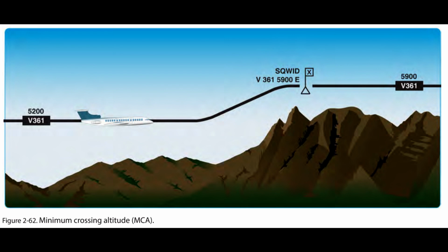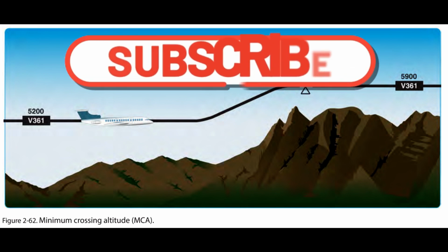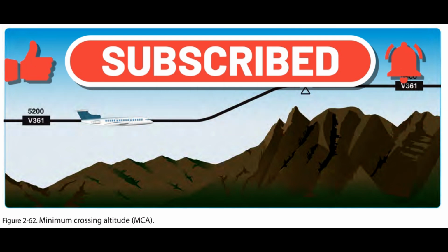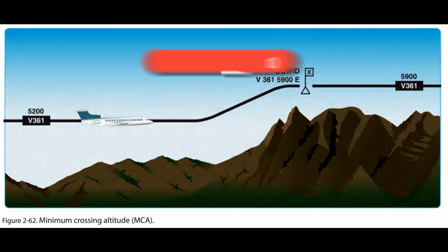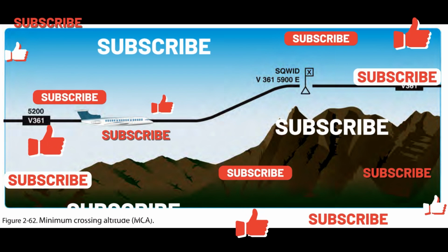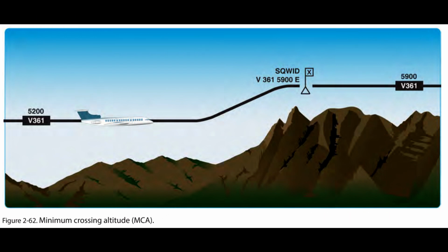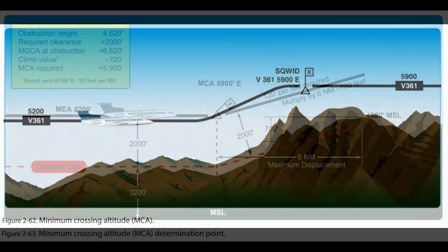The same protected en route area vertical obstacle clearance requirements for the primary and secondary areas are considered in the determination of the MCA. The standard for determining the MCA is based upon the following climb gradients and is computed from the flight altitude. 1. Sea level through 5,000 feet MSL, 150 feet per nm. 2. 5,000 feet through 10,000 feet MSL, 120 feet per nm. 3. 10,000 feet MSL and over, 100 feet per nm.